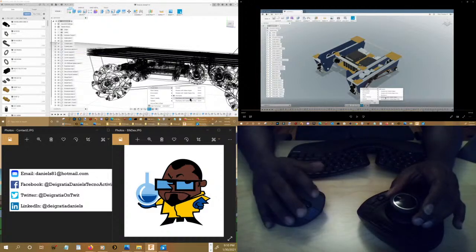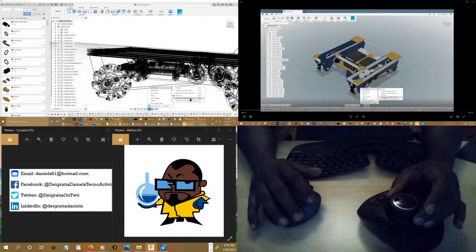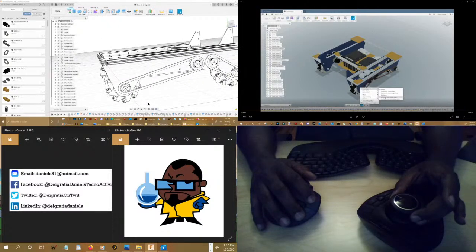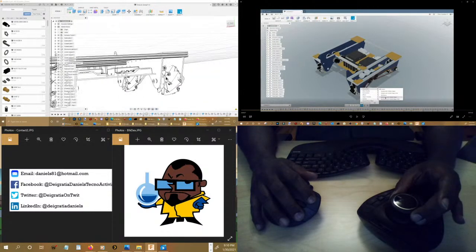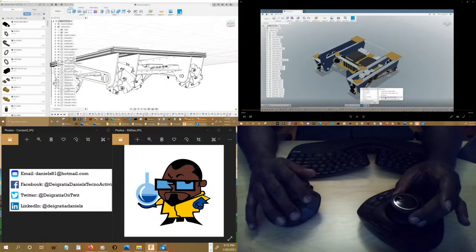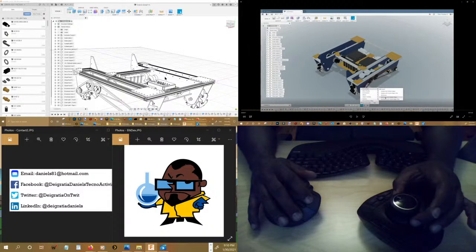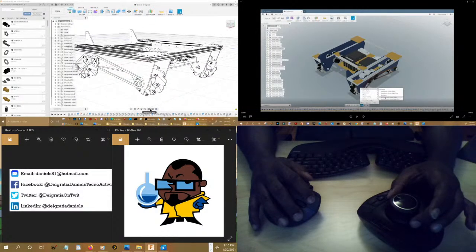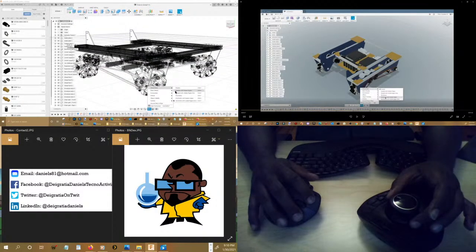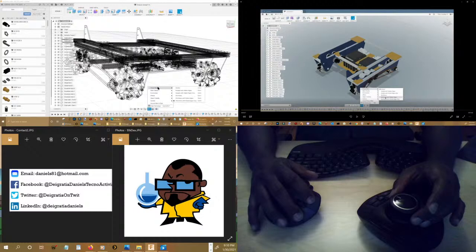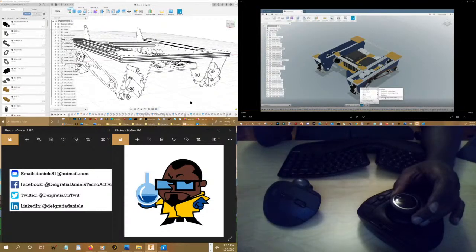So the next one is wireframe and hidden edges. Again, wireframe and things that you can see all the way through. So you can see the edges that are blocked, that you cannot see in real life. So this is kind of like a black and white version of the model. Let's see what's next. I'm sorry, I did it wrong. Wireframe and hidden edges, and what's the next one? And visible edges only. There we go.